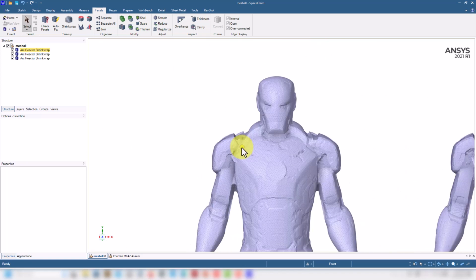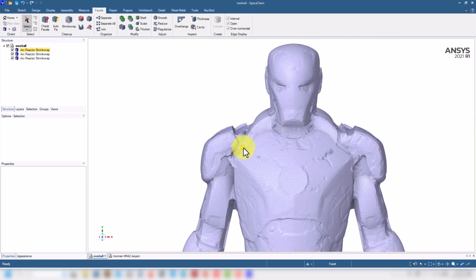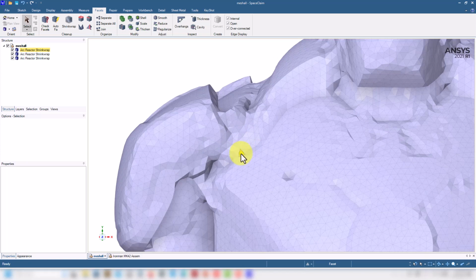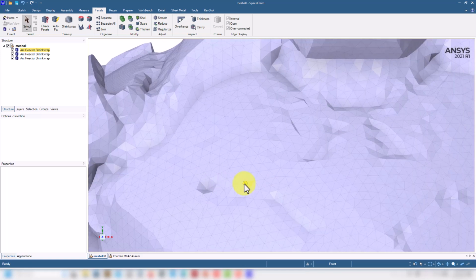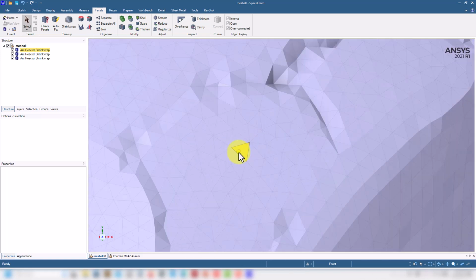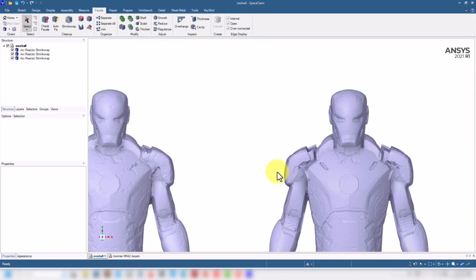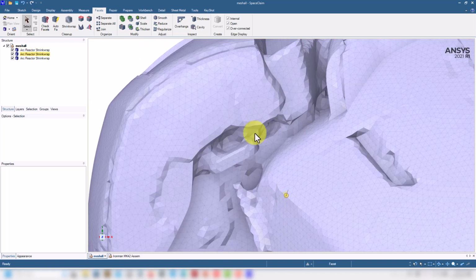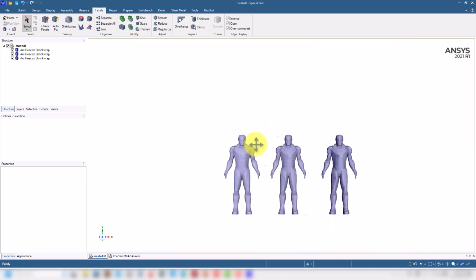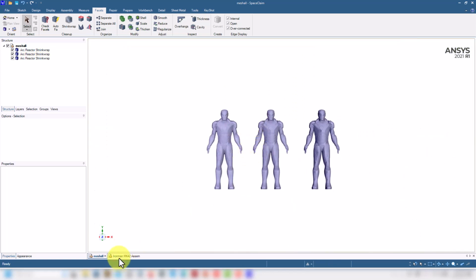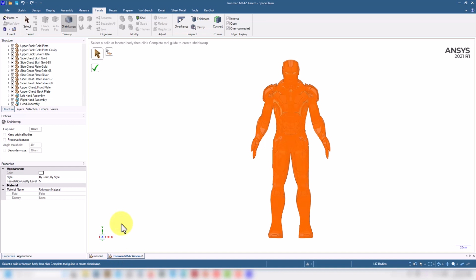And just to show you here, also the value that you choose. If you choose a large value of gap size, you see that it's closing those holes while capturing the most relevant features. In this case, with 5 millimeters, you start to see all these holes and so on, which might not be very important to you. So coming back here, depending on the tool, you will need to define this gap size.